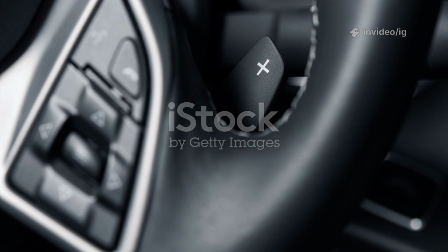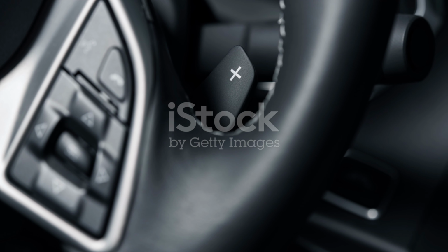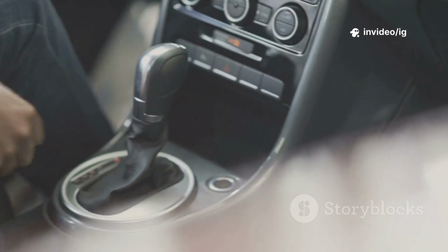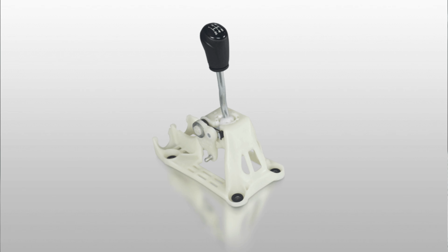Sensor and component locations. Where to find them? To diagnose P0815, focus on these critical components. Upshift switch or paddle shifter, if equipped. Location: on the steering wheel for paddle shifters or on the gear shift lever for manual upshift button. Function: detects when the driver requests an upshift and sends the signal to the TCM. Gear shift lever assembly. Location: inside the cabin where the gear shift lever is located. Function: houses the upshift switch in some vehicles.